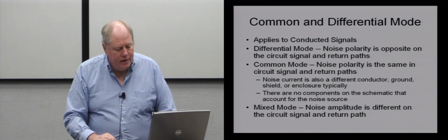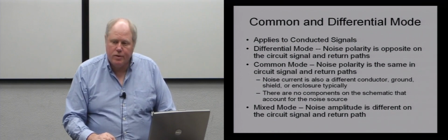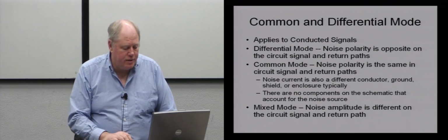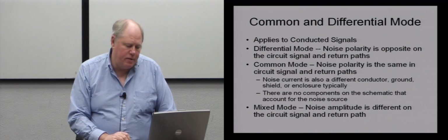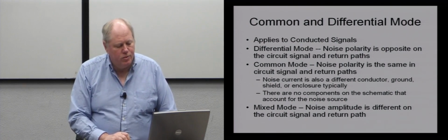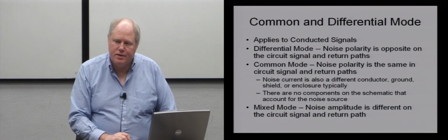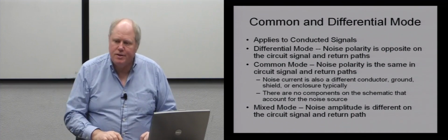In reality, signals are both. There's a common mode portion and a differential mode portion when you have these noise issues. And so pretty much all things are mixed, although they tend to be more dominantly one, common or differential. And there's sort of a rule, where they call it like the balloon or something. If you bring the differential mode signals down, kind of imagine pushing in on a balloon, it pushes out somewhere else. The common mode signals will sometimes go up.